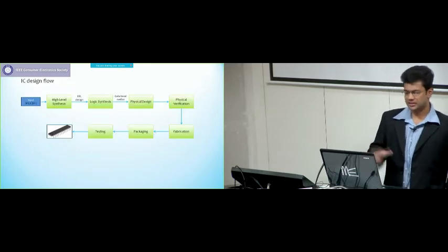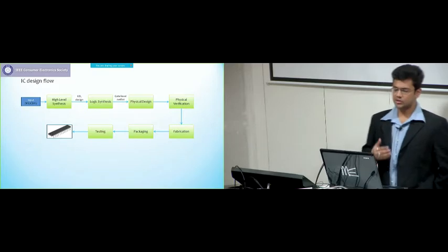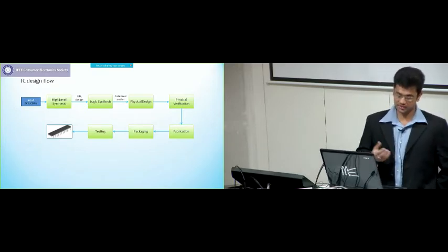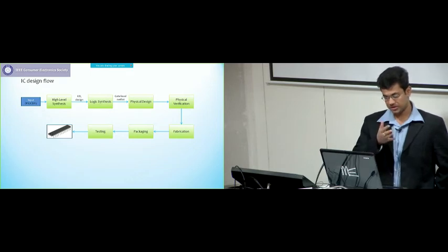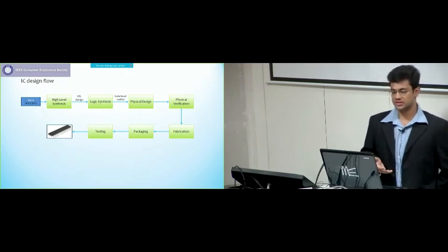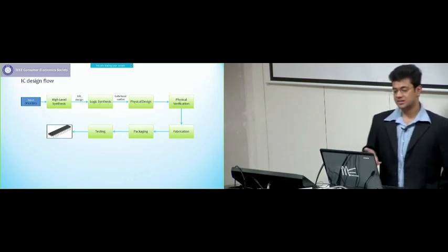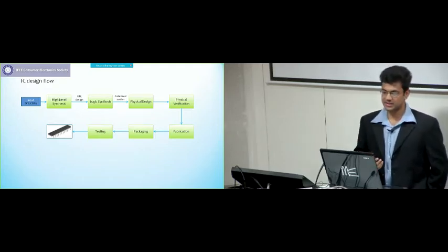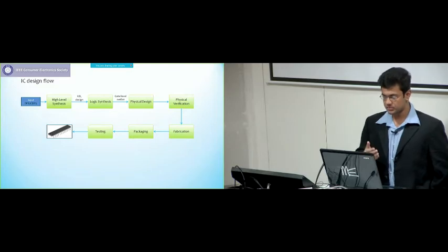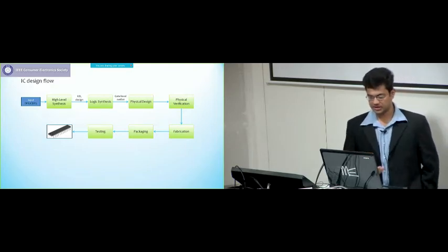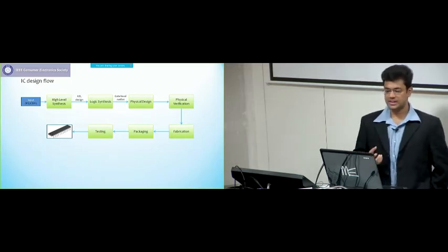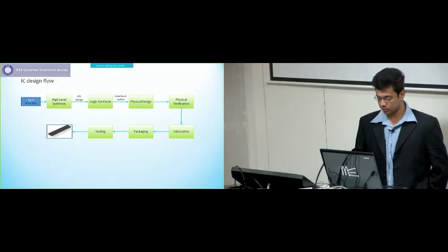In a typical IC design flow, it starts off with the algorithmic behavior of the DSP design, a very common component in CE devices, which is used for performing high level synthesis. The synthesized RTL design is subsequently fed into logic synthesis that generates the gate level netlist, followed by physical design, physical verification, and fabrication. Finally, we end up in the packaging and testing phase, where you get a tangible form of the system on chip that is used for CE devices.